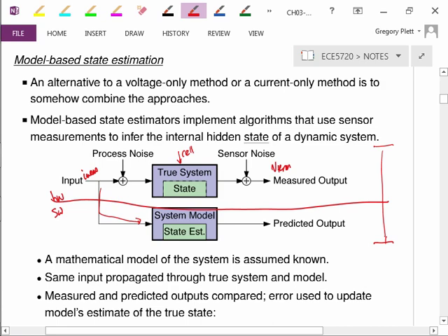And if this is all we did, by the way, this is Coulomb counting so far. There's no feedback yet. The measured current goes into my Coulomb counting model, and I update my state of charge estimate, and who said that doesn't work?